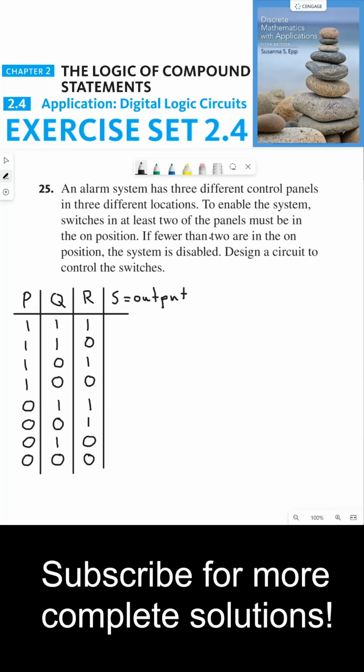According to this situation, to enable the system, or in other words, for S to be 1, switches in at least 2 of the panels must be in the on position, meaning that if at least 2 of these inputs are a 1, then the output is a 1. So row 1 is a 1, row 2 is a 1, row 3 is a 1, but row 4 is a 0 because only one switch is on. And then we can finish this input-output table, and now we can see what makes our output true.